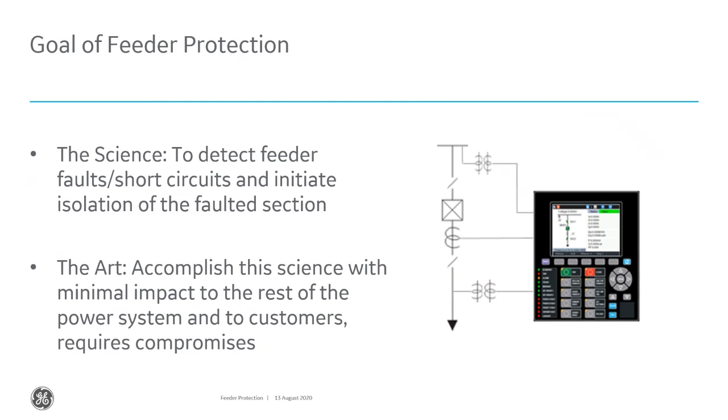However, the consequence of that is if you have a fault outside of that piece of equipment's zone of protection, for example, a transformer that's feeding some sort of load, if you have a fault on the load side, that overcurrent element can be susceptible to pick up and trip, and you're unnecessarily taking out that load or parts of the power system that you normally wouldn't need to take out for a fault in just that transformer.